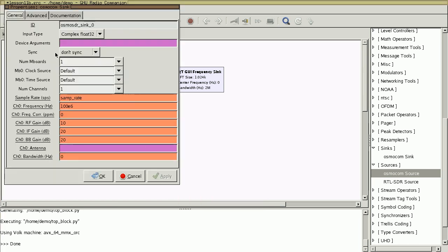Let me take a look and see here. This should be 27 megahertz because that's the same frequency that I used to capture. Now remember that the signal of interest is actually at approximately 27.15 megahertz. It's 150 kilohertz above that center frequency of 27 megahertz in our capture file. If I want to replay it and have it remain 150 kilohertz above 27 megahertz, then I need to have my center frequency exactly the same for my replay as it was in my original capture.